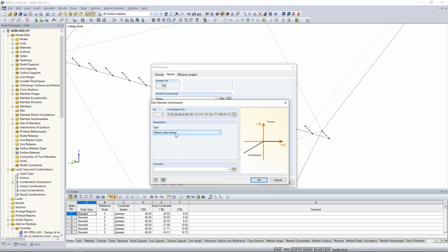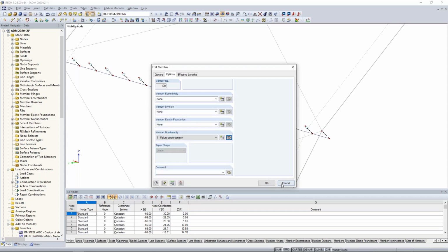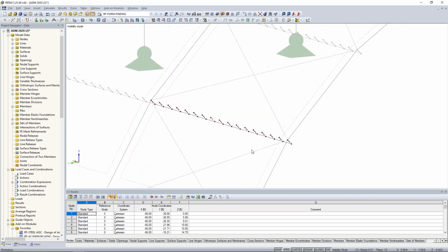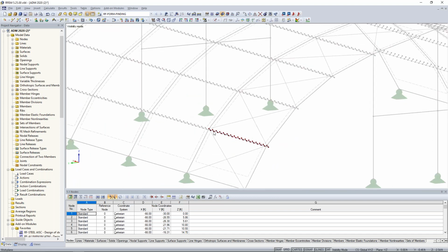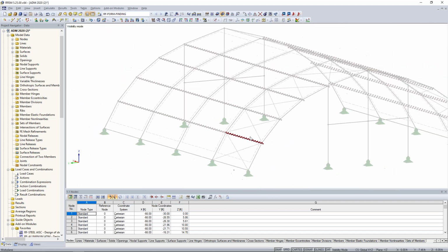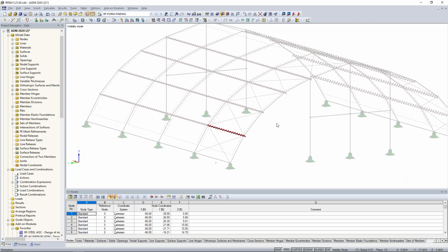This will make a little more sense as we view the deflected shape under the various applied loads. So I just wanted to briefly explain what all of these various nodes are at these truss elements. That was to tie together the fabric membranes with the tube elements, giving us the ability to apply these nonlinearities to take into consideration the true behavior.